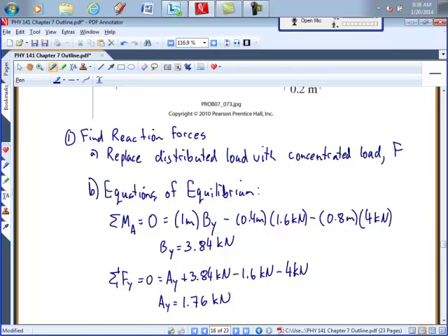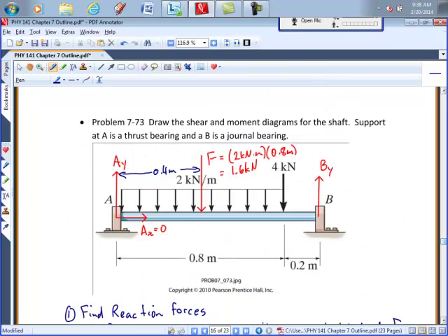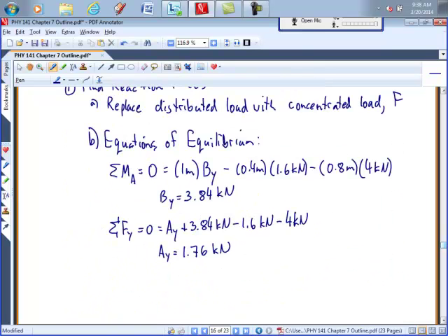All right. So we could do the section cuts and figure out the shear and moment as a function of x, like we did in the first section, or we can just use what we know about the relationship between the distributed loading and the shear force and moment diagrams to produce them. I'd say using calculus, except we're not actually using any calculus. We're using the concepts of calculus, of one function being the slope of the other.